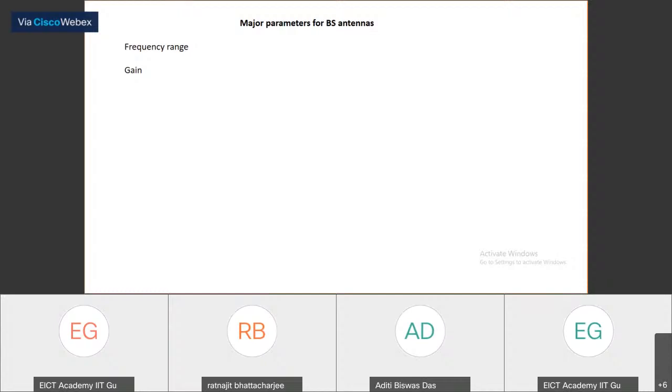So this directivity is going to be a function because you are finding out power radiated per unit solid angle, that will vary with theta and phi. I hope yesterday when we discussed the basics of antennas, these were discussed in detail. I'm just repeating some of these. So D is a function of theta and phi, and directivity is the maximum of this directivity function.